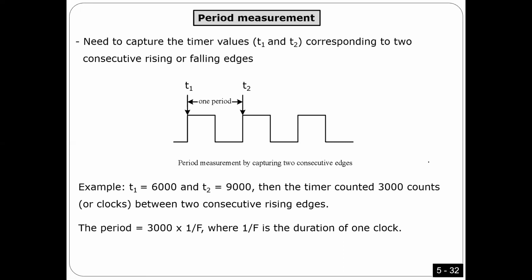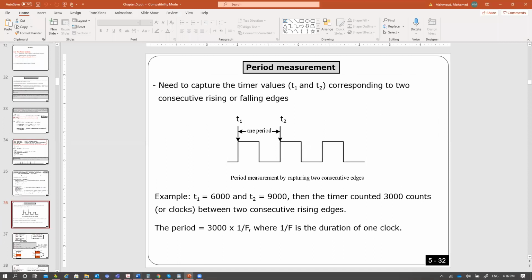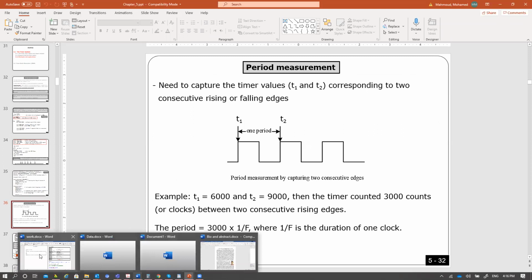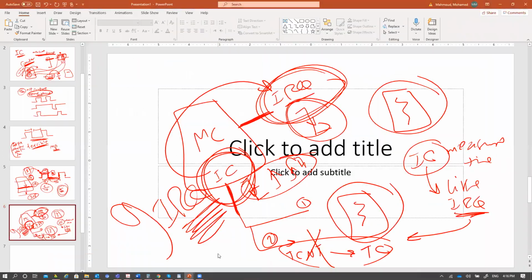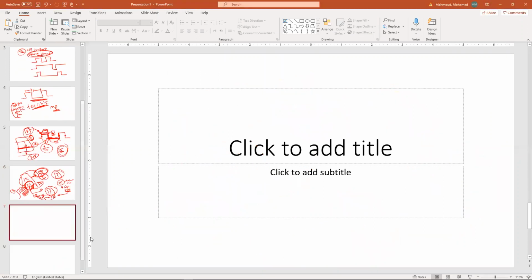Now again, I didn't use it as input capture to measure time, but I used it like an IRQ, which is interesting because we don't have too many IRQs. We have only one IRQ. Sometimes you may not need all the channels to measure time, so you can use one of them as input capture as an IRQ.